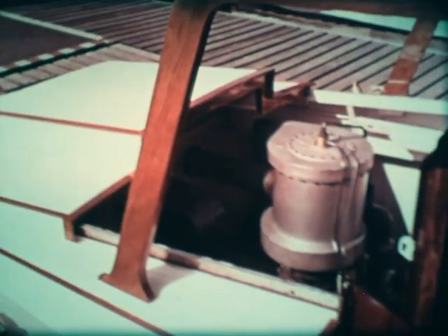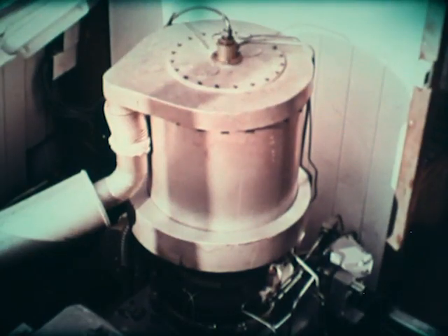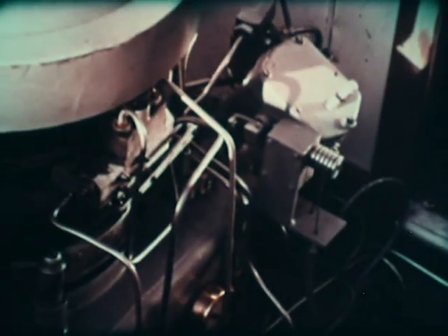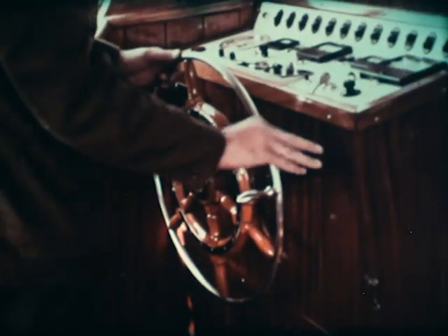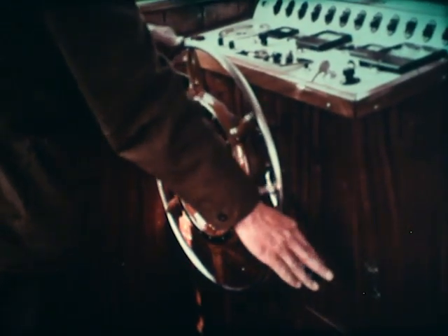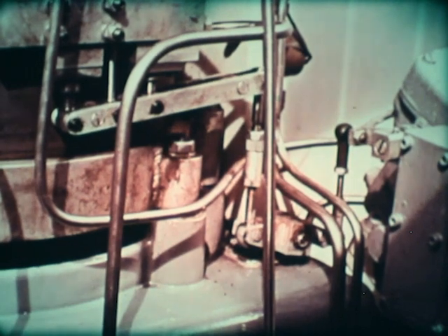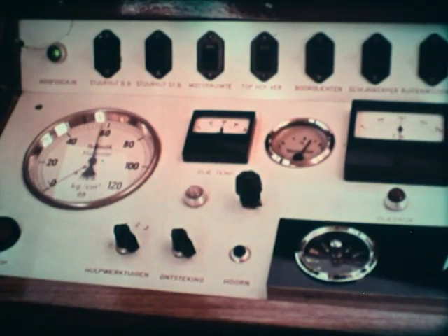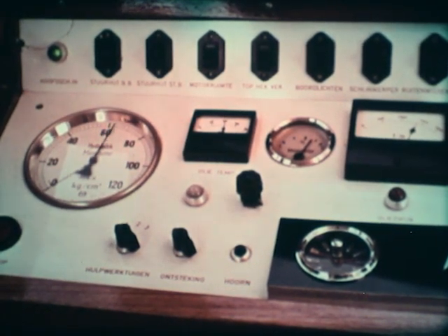The large cylinder is the preheater fitted around the head of the engine. The fuel atomizer is seen at the top. The power output of the engine is proportional to the mean working pressure. If the governor is set to a higher speed, helium from a high-pressure bottle is blown into the cylinder, quickly increasing the working pressure and the power. The pressure also controls this variomatic drive of the blower that supplies the air required by the burner and keeps the air-fuel ratio constant.